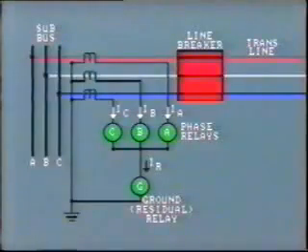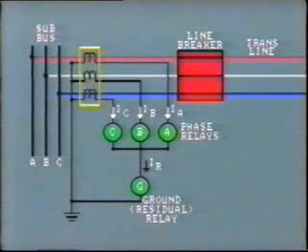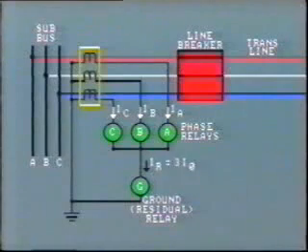However, every major transmission line should have its residual current monitored. Where CTs are Y-connected like this, we can conveniently measure residual current, or 3I0 current, in the neutral return circuit. These are the same CTs that provide input to the protective relays for line protection.